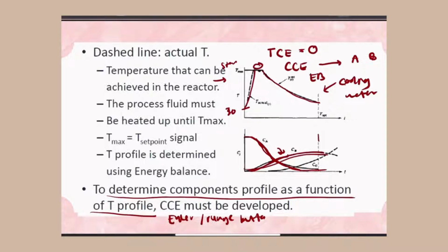However, when it goes right here, we can see that B starts to decrease. This is because at this point the reaction starts to happen and B starts to form C. So we don't want this to happen because our desired product is B and C is our undesired product. So we need to stop before C is formed